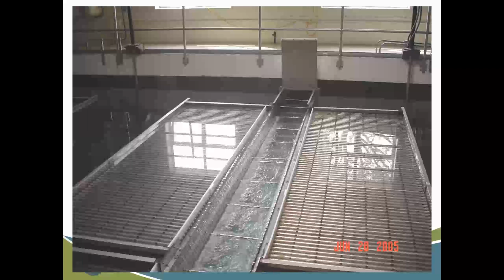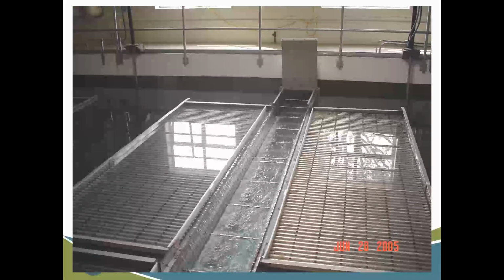Here's another image of one of those retrofit projects that I was discussing. I think this is one of them along the Lake Michigan shoreline. I've seen a few of them like this, but there's not a whole lot to see when you're actually at the plant. But the amount of difference that this makes is just huge. The footprint of the facility is greatly reduced, and the amount of residence time in the settling basin is greatly reduced to accomplish the same goal as a conventional settling basin.